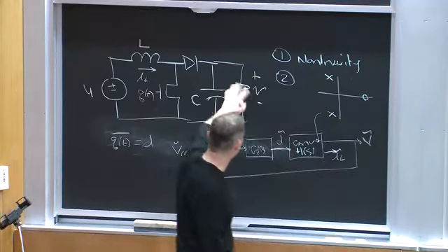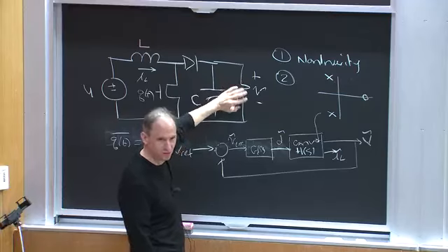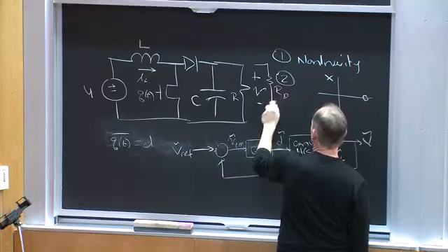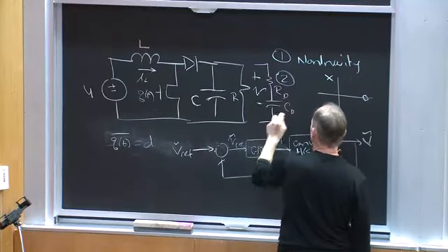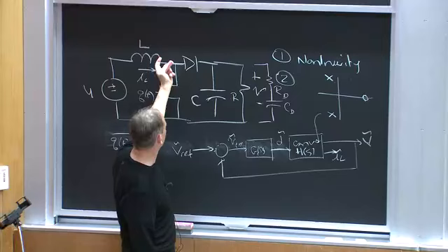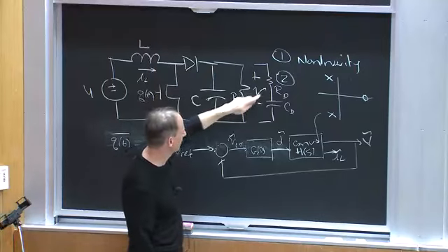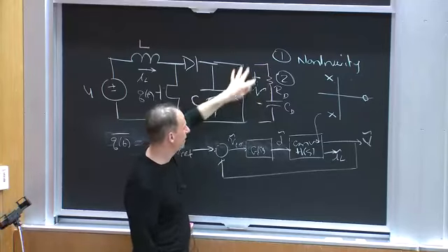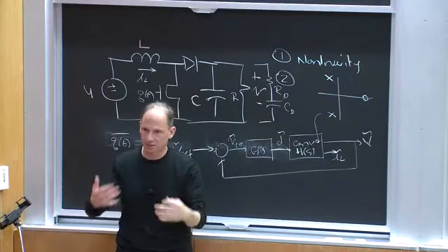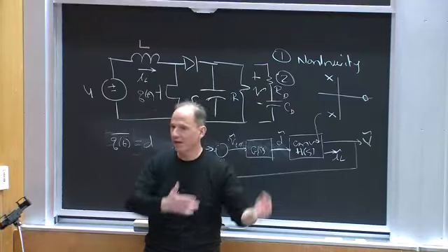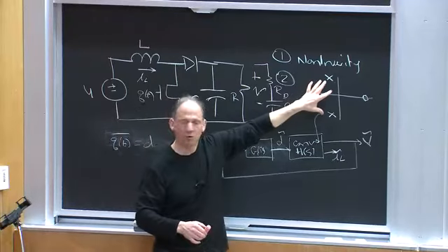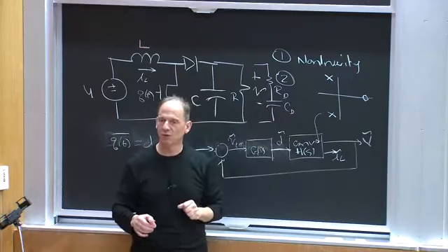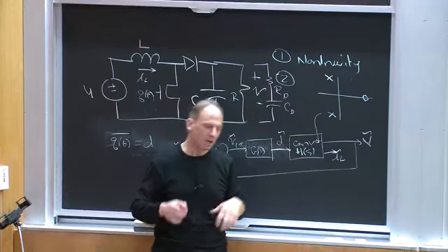So we said, oh, it's this resistor that's damping the poles. Maybe I could go add RD and CD, such that CD is a short circuit near the corner frequency where the L and C are oscillating, so RD serves to damp it, and RD doesn't vary. So by picking additions to my plant, by changing my converter, I can help make things better damped and maybe get better pole locations here. I'd have another pole location, but maybe it would be a low order, over-damped pole location. So that's one thing I can do.